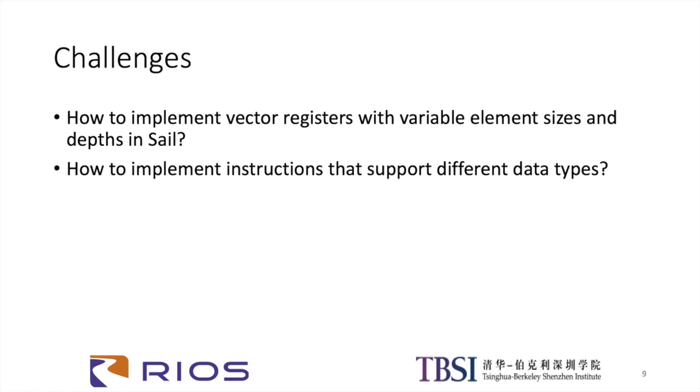Now, let me talk about the two major challenges we've been through. First, how to implement vector registers with variable element sizes and depths in Sail. Second, how to implement instructions that support different data types.